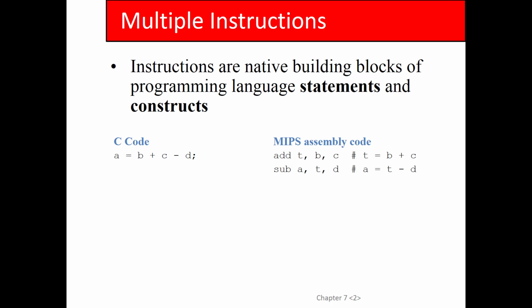Well, we've got adders, subtractors, comparators, floating point units, and RAMs. RAMs of various configurations and types. We have small RAMs and big RAMs, multi-port RAMs, right? And also there's just basic digital logic that we can use. Oh, and we can also create controllers as finite state machines, or we could create lookup tables, like as logic gates or as RAMs, right? So how do we get from that to having a processor that works, that executes programs?